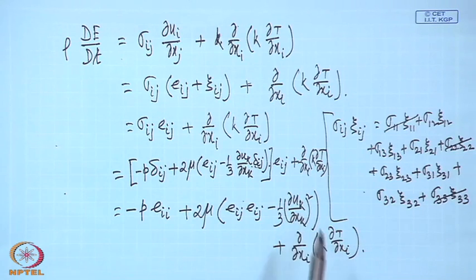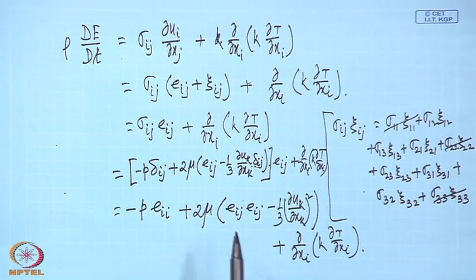The second term is simply 1/3 of E11 squared plus E22 squared plus E33 squared, and the first term contains E11 squared, E22 squared, E33 squared, also many other terms, which are also square terms. All the terms are square terms. So the second term can never be larger than this, and since all the terms present here are square terms, this second term can never be negative.